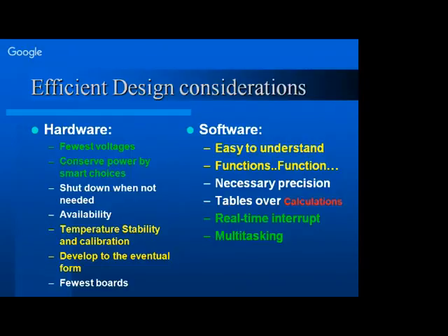So few voltages, what does that mean? Let's say you are developing an industrial application, and your chips are working on 3.3 volt, and then you are connecting an LCD of 5 volt, which needs DC 5 volt. You will see that your board now needs more than one voltage. It will require 3.3 and 5 volts. So what is the big deal, you would ask? You will have to manage everything. You have to manage the power, and you may have to select some power management IC, or you may have to connect two regulators, 3.3 volt and 5 volt.